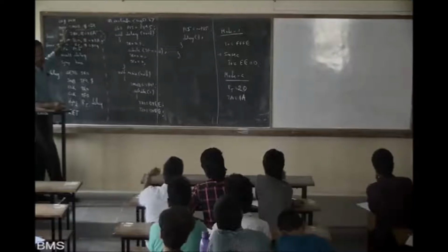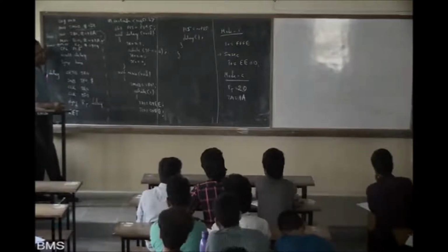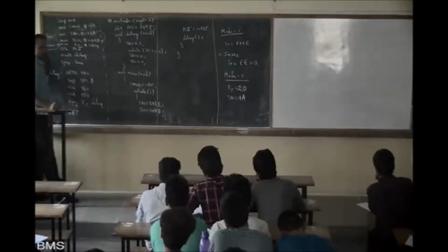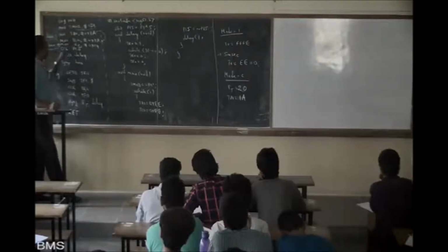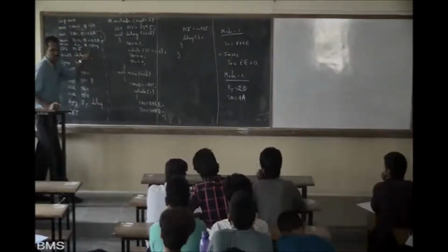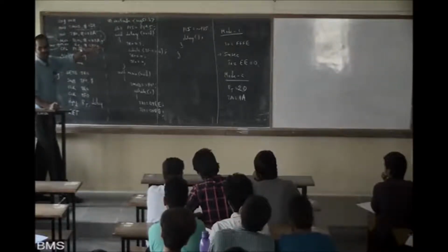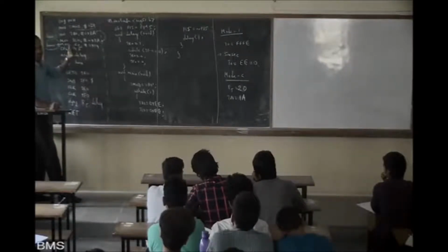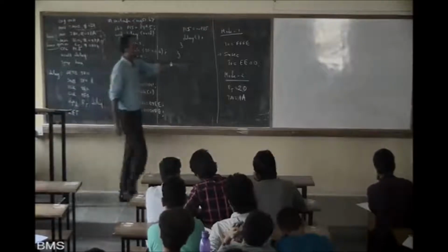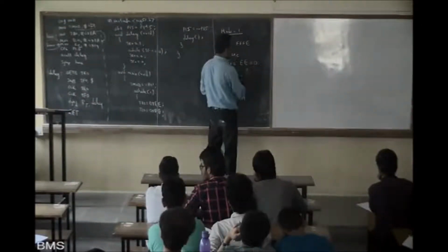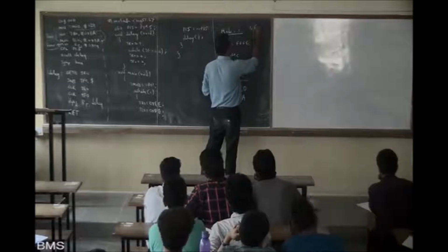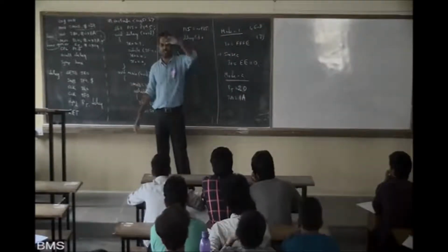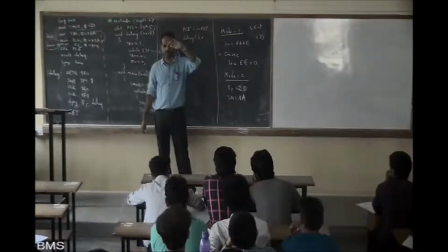Guys, very important thing is the same program structure. You should know where to give the value here. This is the second change. This MOV R5 is required only if the count value is more than 256. If it is below that, directly this only. MOV R5 is required here because the count value we had was 4608. If the count was 4608, then you don't require R5 in the simple case. Then the program becomes exactly similar to the original program.